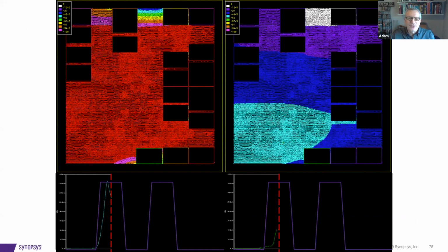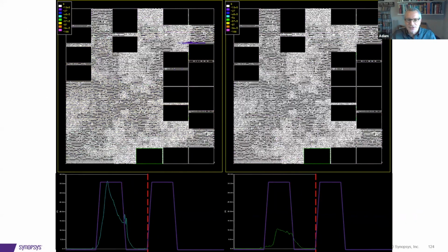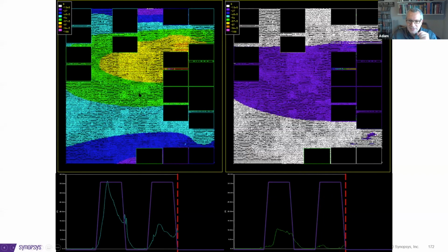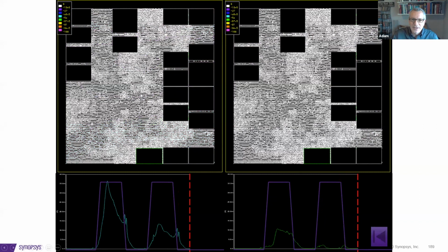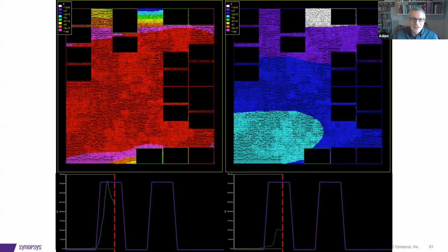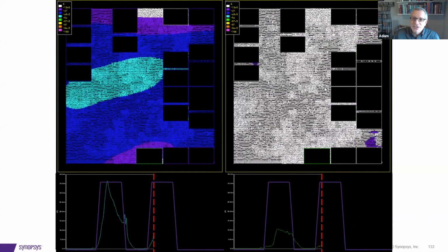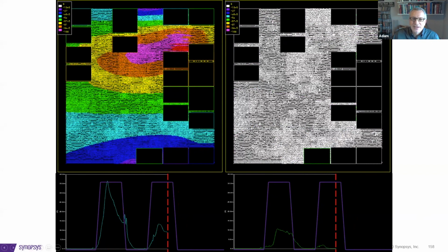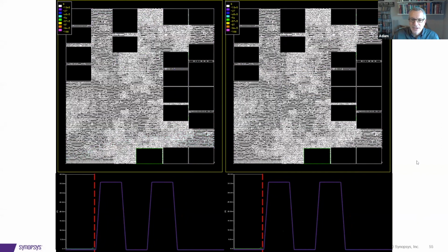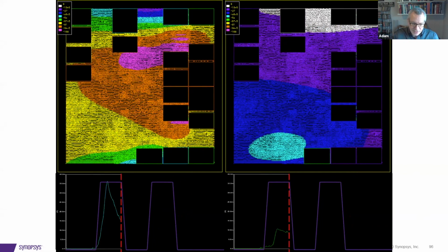You can see that without some kind of mitigation, whether it was ATPG or some kind of hardware mitigation, you can get a lot of power draw, and it shows itself differently depending on where exactly all the switching activity is happening. In this case, it's a small design, so it's happening all over the place. It's bad. But with some mitigation on the right-hand side, you can see you can still get good, decent results and low power results if you play the game appropriately. So I'll show that one more time, and then we'll get into some more details about correlation.